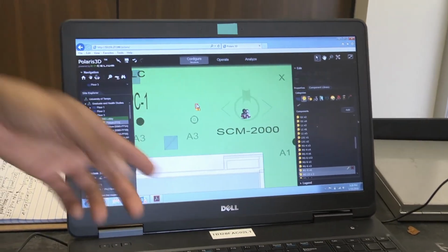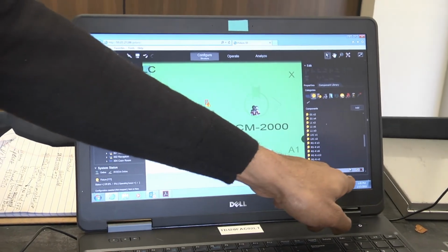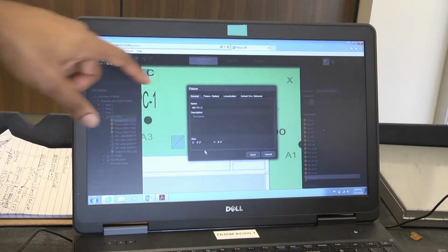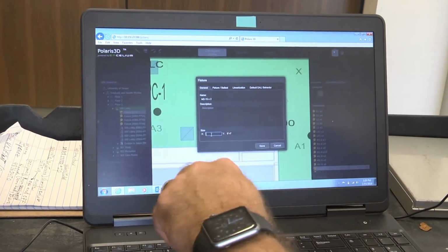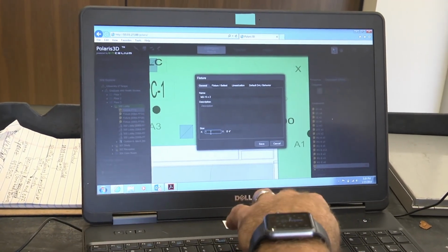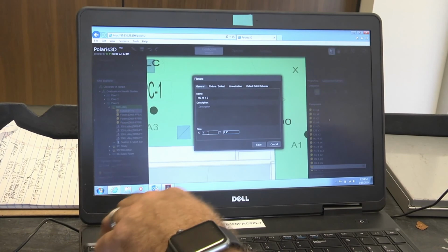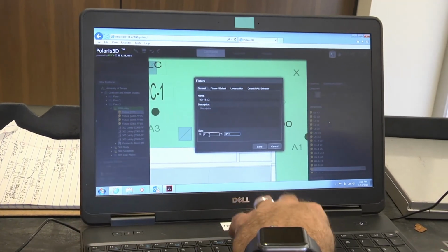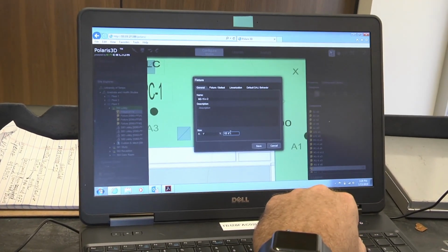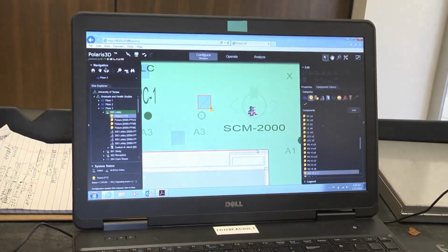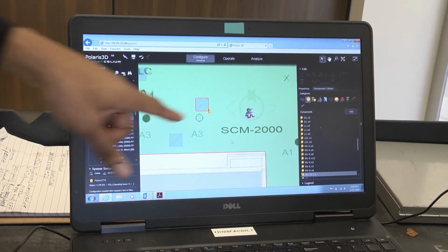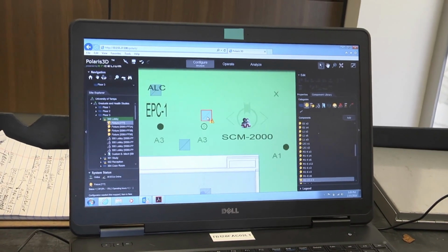So now change it. Just go back, hit the pencil, go back to edit, and then change those back now. So put it to 1 foot by 1. So 1 dash. Yep. Same thing for that one. One dash. Get rid of the stuff in there. Okay. Now hit save. And there it is. You see? It's easier for you to map, right?